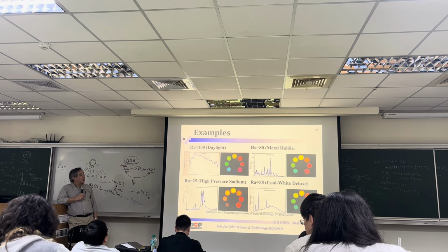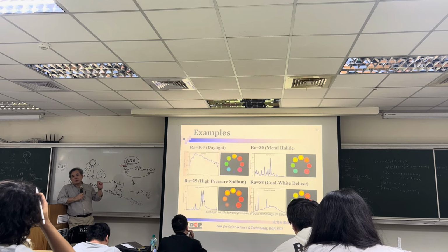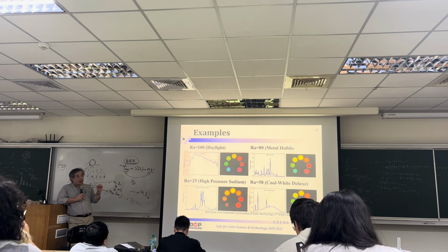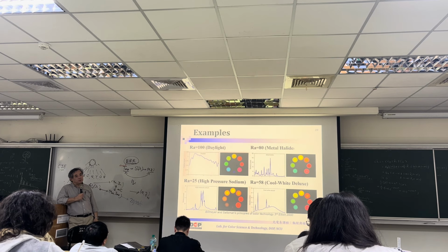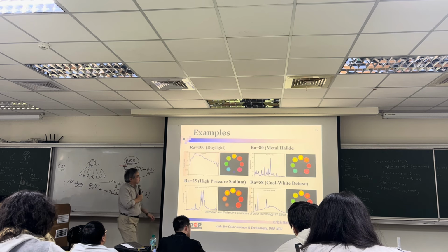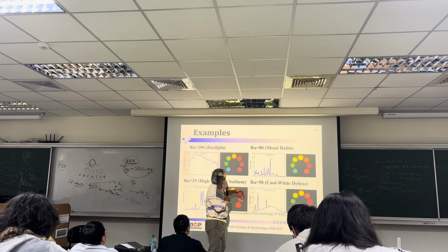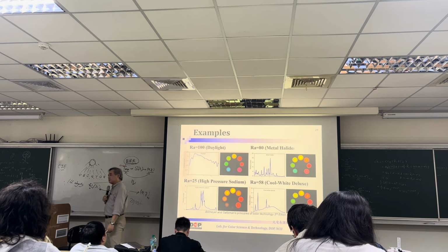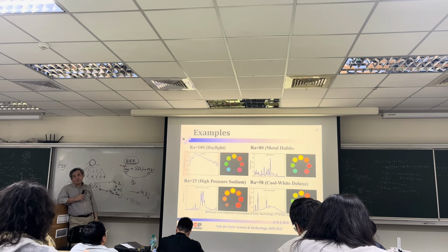It means if the CRI difference is within 5, the quality is not so different. Okay, so it is a rough index. So we won't say 80 is better than 75, but it is better than 70. Okay, if the difference is within 5, it is almost the same.